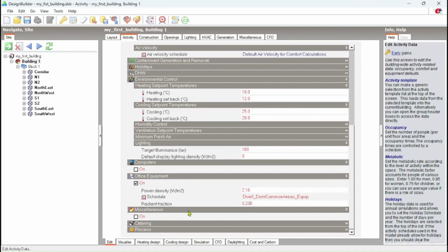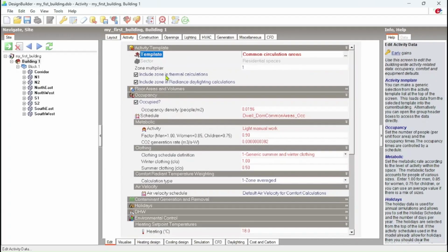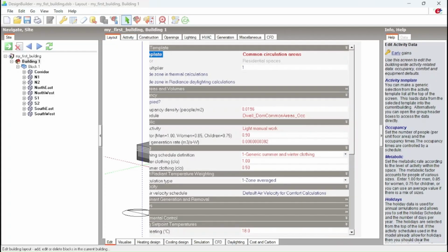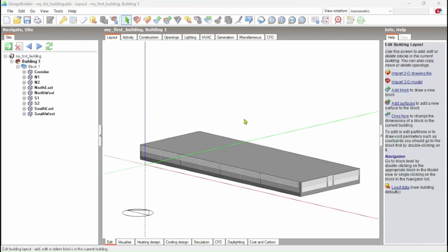So what else we have here? As you recall, these are all the information about the internal gains of a building. So this is very important to define. So the last key element that we need to define before running the simulation are the air change mechanism. As most of our buildings are going to have some control of natural ventilation, we are going to define this natural ventilation, and we are also going to define the infiltration.